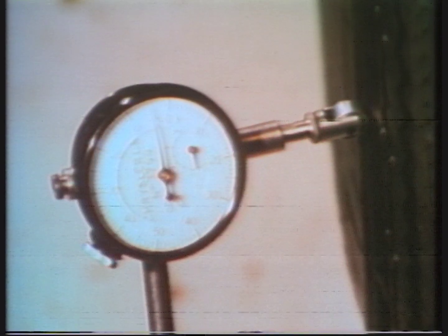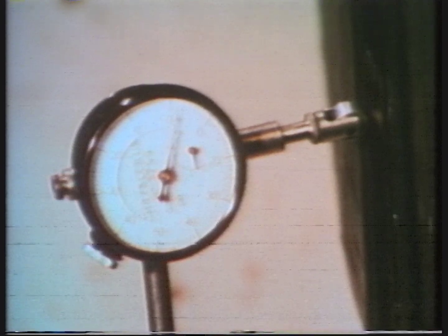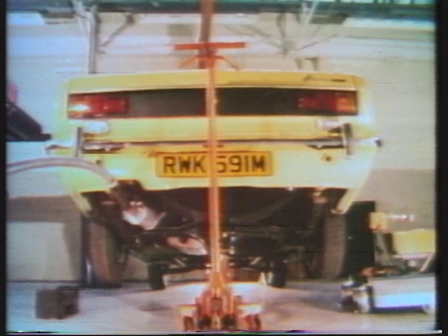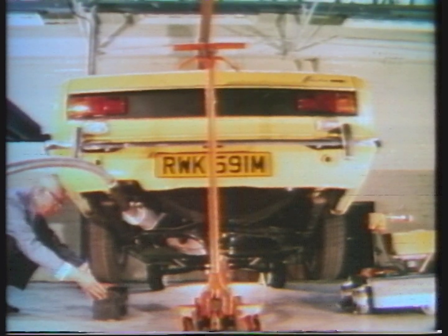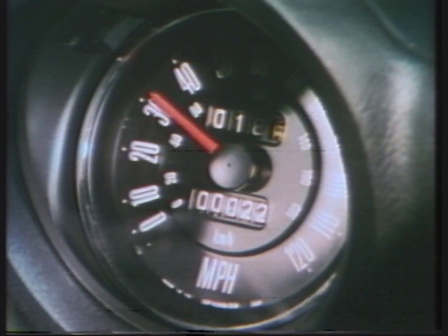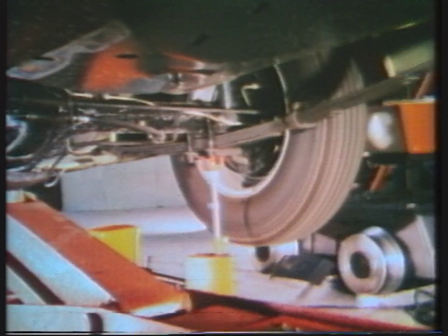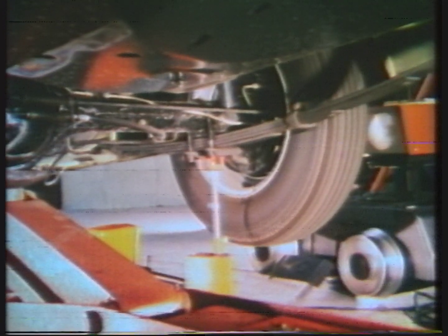The basic cause is kinetic unbalance of rear wheels. Very careful attention to preparation, particularly to the radial and lateral runout of tires as previously described, again applies. Remember the 3 precautions to protect your customer's differential gears. Horizontal on jack, top gear, 35 miles per hour maximum, shortest possible time run, maximum 30 seconds.